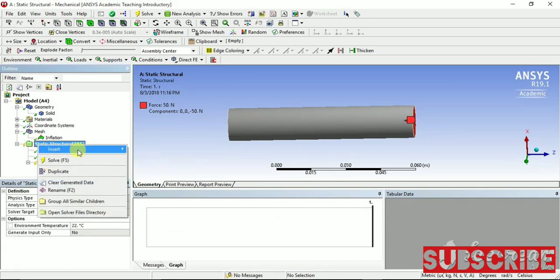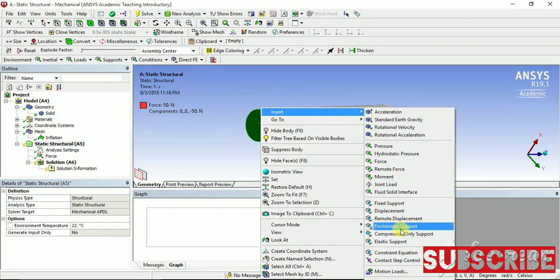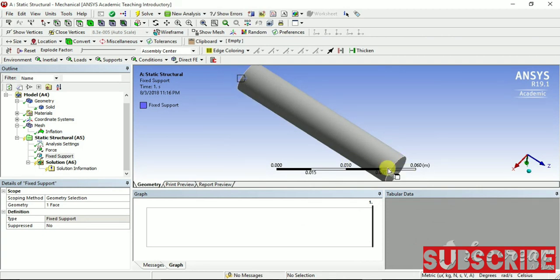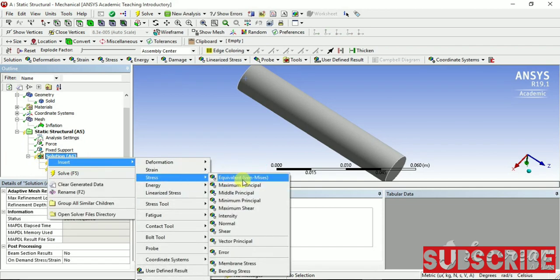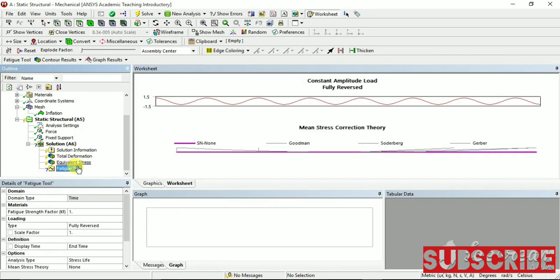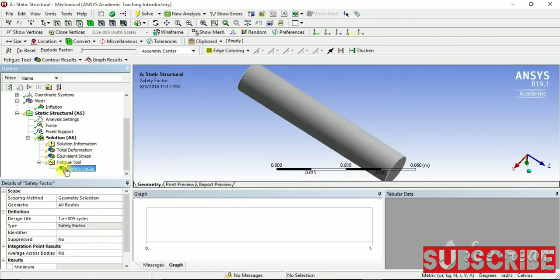We have applied the force, but we have not given any support, so we have to give a fixed support to it. So now one side is fixed and on one side a force is applied. Now you can see the question mark is not present here because the load is defined. Now we have to see the results. We can see different results here. In the fatigue tool we can see the factor of safety, so that we know whether it will survive the load or not.